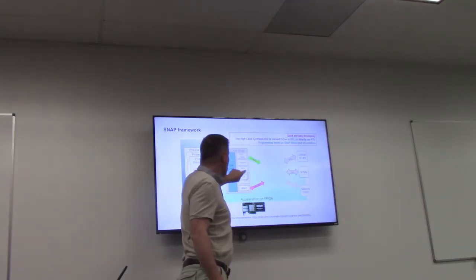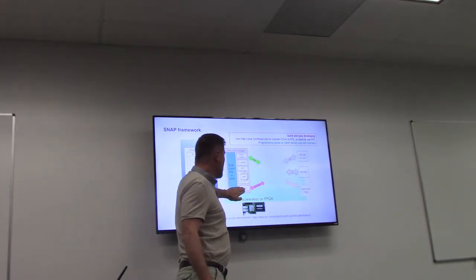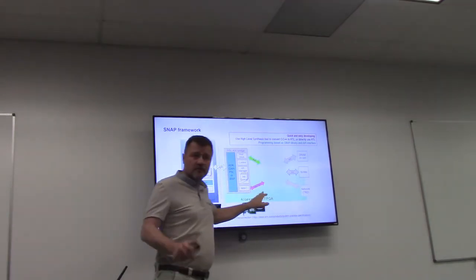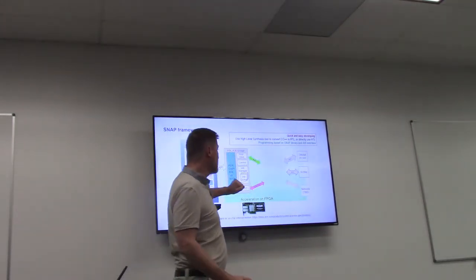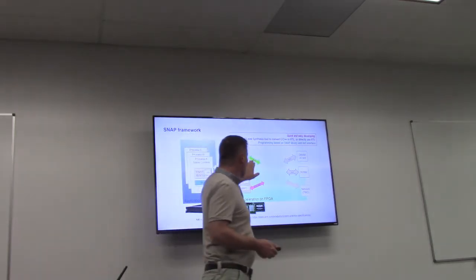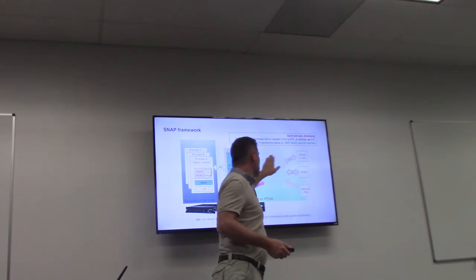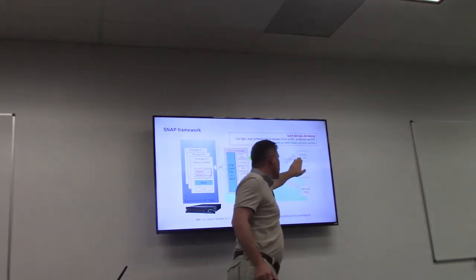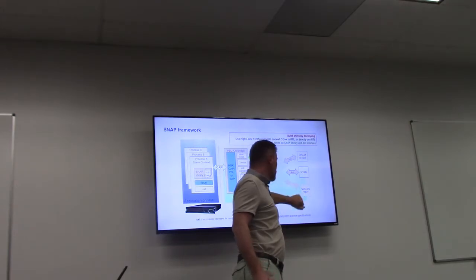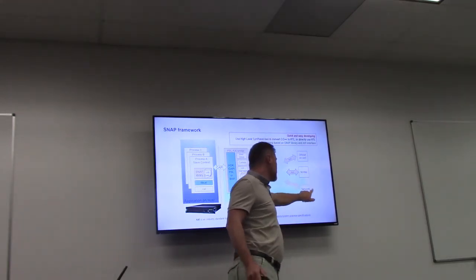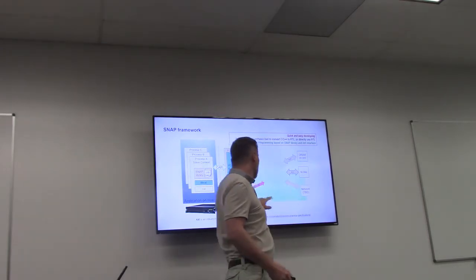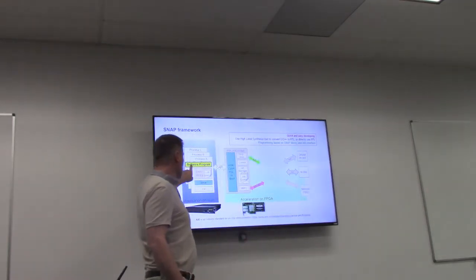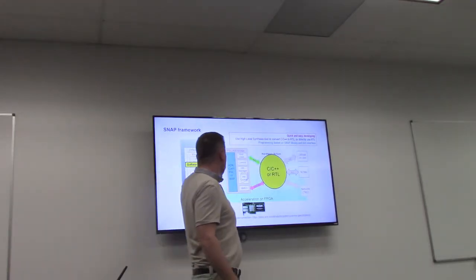It offers the job manager, a DMA, the control logic, the MMIO to access a very low-speed link, all the registers that you need to control, and we can enter into the details offline if you need. For the hardware guys, we use some links to interconnect whatever DDR, whatever SSD you have as an I/O, whatever network as an I/O. It's IP-based because nobody has provided an open source network controller for the FPGA, so we need to rely on IPs. Okay?